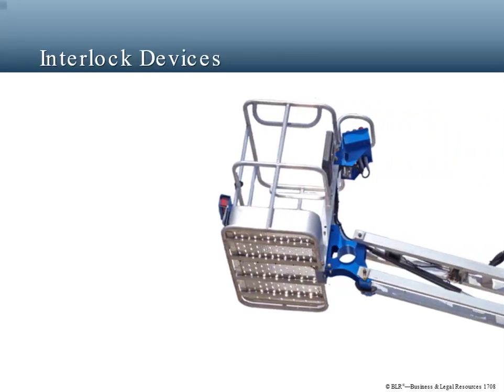Many aerial lifts are designed with interlock devices that help prevent an operator from accidentally exceeding the stability requirements of the equipment and tipping over. A common interlock device is the driving interlock, which prevents the unit from moving or being driven unless the platform height or platform configuration is adjusted to meet stability requirements. In other words, the platform will need to be lowered before the equipment can be moved.